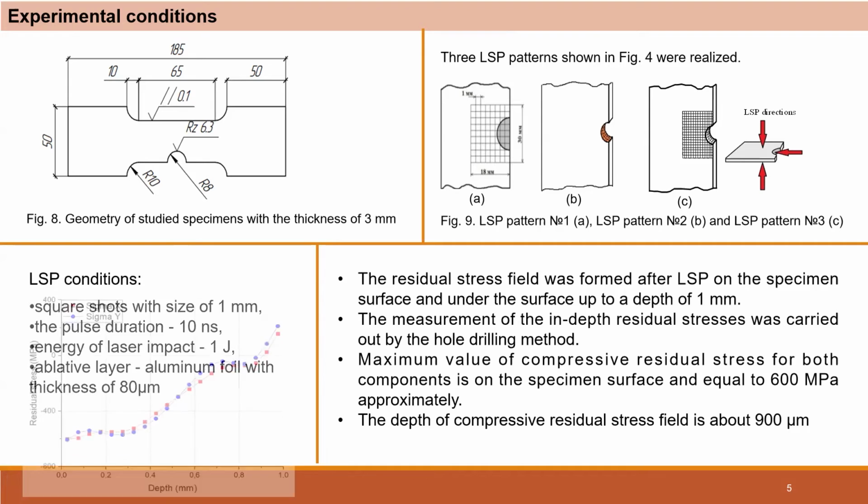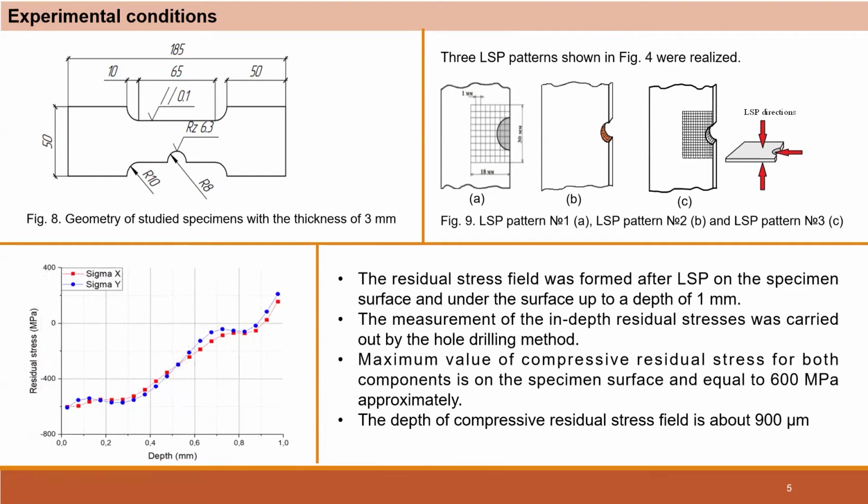After that, we measured the field of residual stress using the hole drilling method, and we see that the maximum value of compressive residual stress is about 600 megapascals, and the depth is about 900 micrometers.